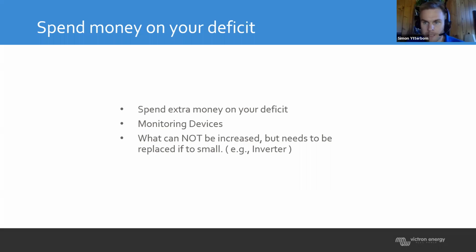Always make sure that you get the right size inverter. If you buy too small of an inverter, generally you need to replace it with a larger inverter. You can't just tag one next to it. There are certain inverters that can work together, but dialing in the size of the inverter from the start is pretty important to save money.